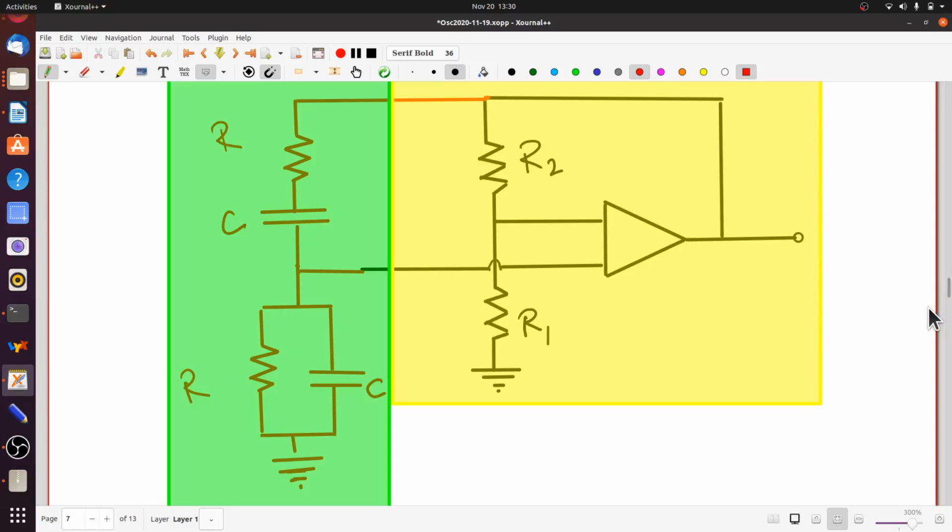In modern circuit applications, we are usually not going to use this oscillator in a situation where there are such large currents involved that an incandescent bulb can heat up too much. So we need to introduce some other kind of nonlinearity. By the way, if you keep R2 by R1 tuned very close to 2, then it's even possible, especially if you have an old op amp, that the oscillator might be able to self-limit the oscillation just short of saturation so that you can get a sinusoidal oscillation even without any further circuit components. But that would be sort of relying too much on the amplifier not being able to do its job too well.